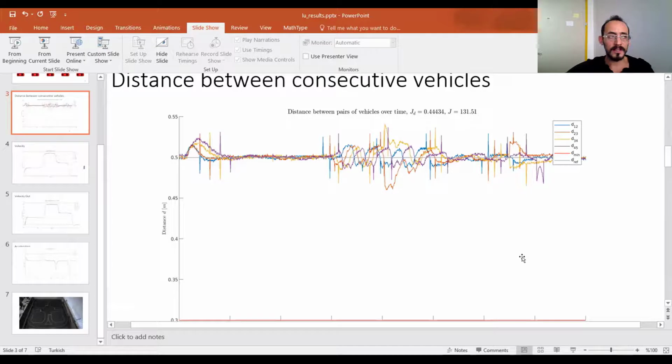So we just skipped the detail that the corresponding row of the weighting matrix Q, the second row, corresponding to the velocity tracking, was set to zero. So the highest priority vehicle was not supposed to be tracking the desired velocity profile. It was only interested in the reference trajectory, 1.1 plus 0.15 sine t trajectory like this.